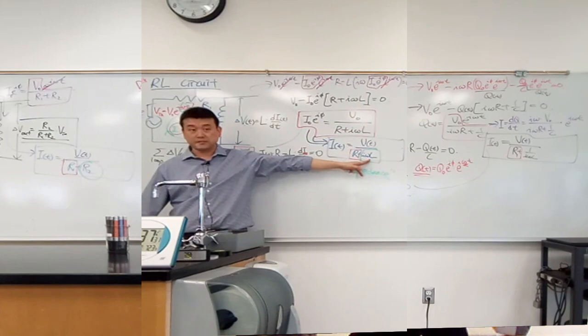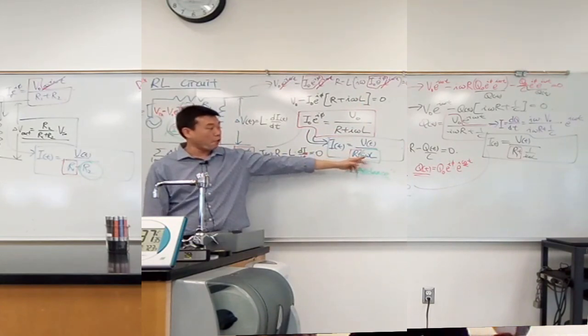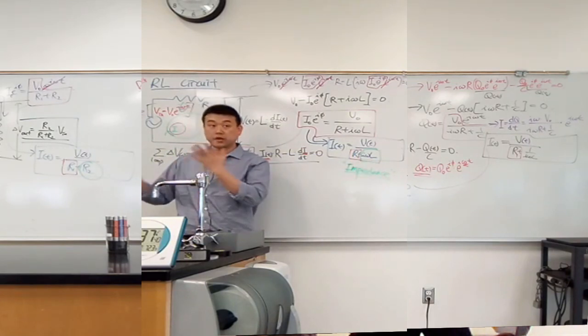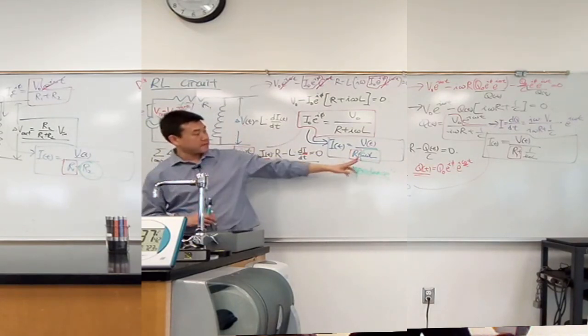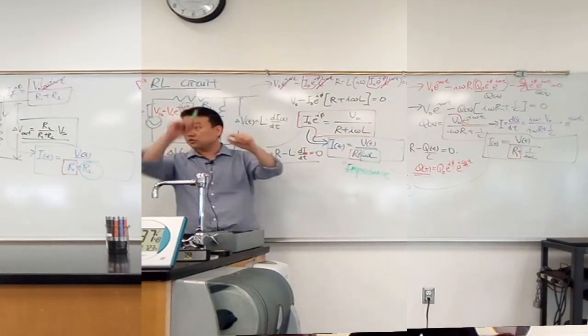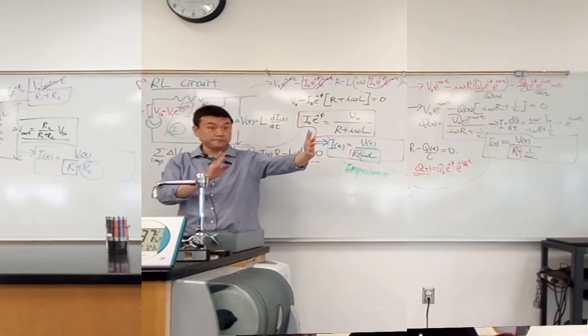That's where the math is simpler and it's easier to make the connections. So this I omega L is a kind of resistance we associate with the inductor. And it sort of makes sense. The higher the frequency, the more the inductor resists current, because the change of current has to happen faster, so the voltage needed across the inductor is larger.